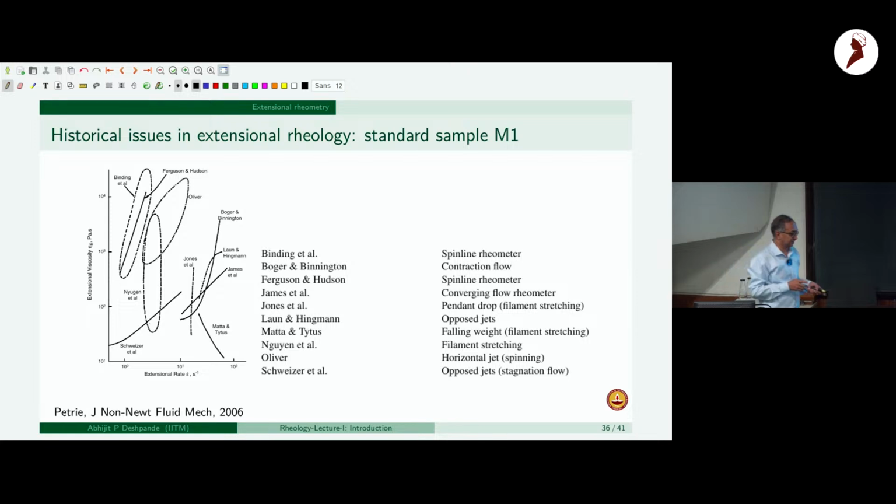So in the polymer literature, as far as the molding operation goes, the high shear rate is still measured using capillary viscometers. With rotational rheometry, we can't really go to very high shear rates. So the high shear rate rheology is done using a capillary viscometer, as far as molding and pushing through small dies is concerned. The measure of viscosity they get using capillary rheometry seems to serve them well. But the stretching part of it is still not as well understood.